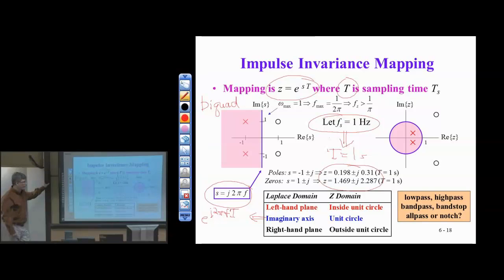All pass is correct. So Appendix O in the reader. So again, also from the slide I had up earlier, 6-8. So we have pole and zero locations that are on the same angle, and the zero location in radius is 1 over the radius of the pole location. So for that configuration, we end up with an all-pass filter.